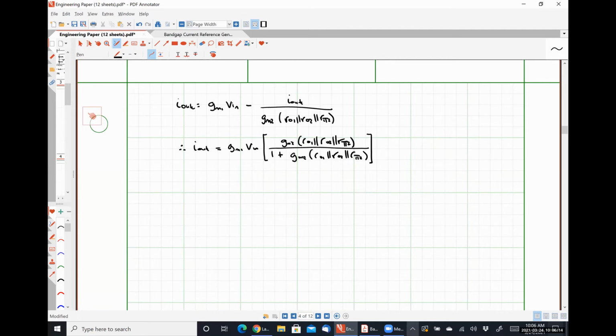But because we're dealing with BJT technology, if we are not using discrete transistors, meaning we're designing this to be manufactured, the transconductance of both transistors should be practically identical because they're both carrying more or less the same amount of current. They're stacked on top of each other, and there is some bias current flowing through both of them. So we could argue that IC1 is going to be really close to IC2.